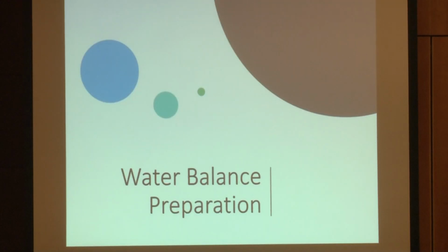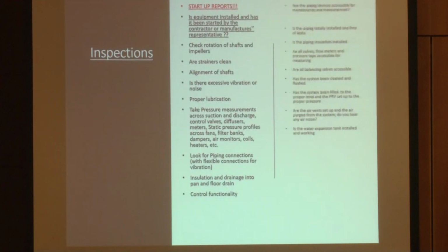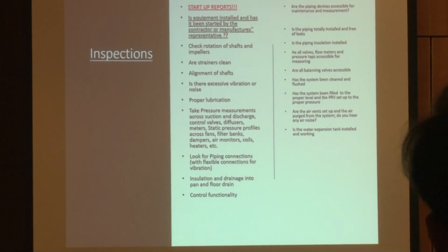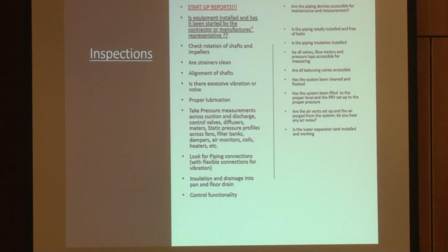When you're trying to start the water balancing process, it's the same as you did on the air side. Walking the job, making your inspections and observations is so very important, because people will call you all the time and tell you everything's okay and everything's ready for you, but that doesn't always happen.